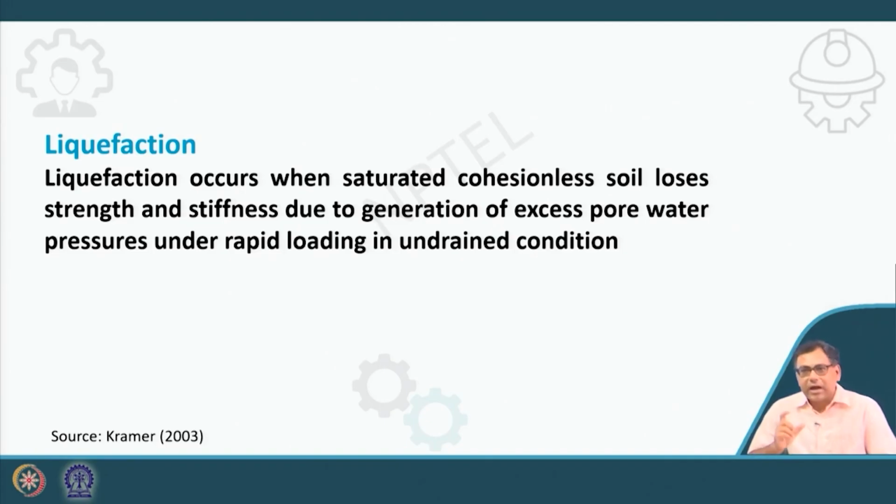It is undrained condition because the loading is of very short duration, and because of the generation of excess pore pressure the soil loses its strength and stiffness, so that is called liquefaction.